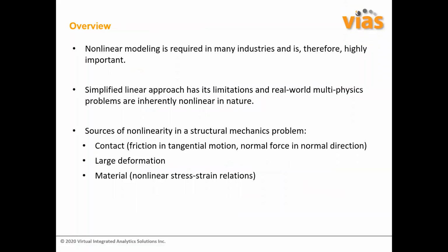I'm assuming that most of you might be advanced users. Some of you might be new users to Abaqus, but we all know from our background that most of the modeling which is required in real industry is inherently nonlinear in nature. A simplified linear approach has its own limitations and may not always give you accurate answers. And whenever you are dealing with contact or material nonlinearity, then you simply have to revert to nonlinear modeling.